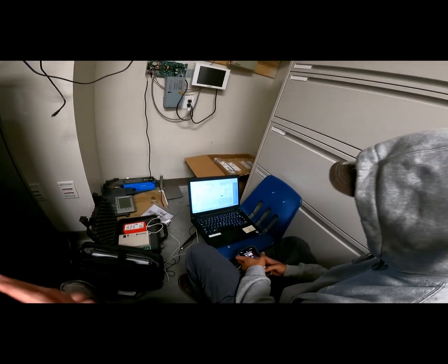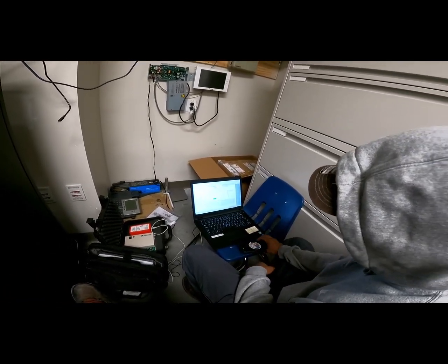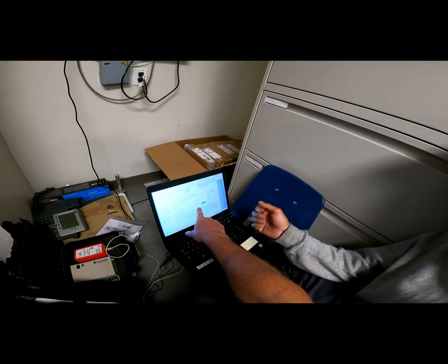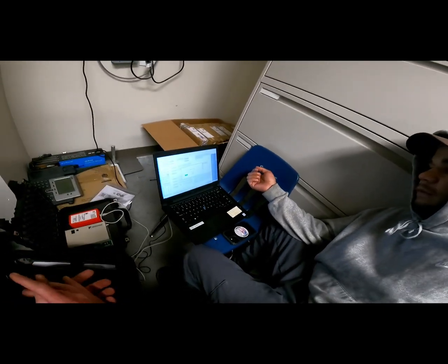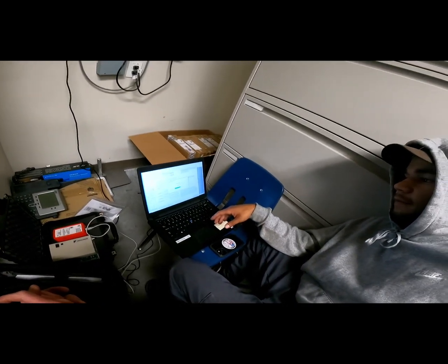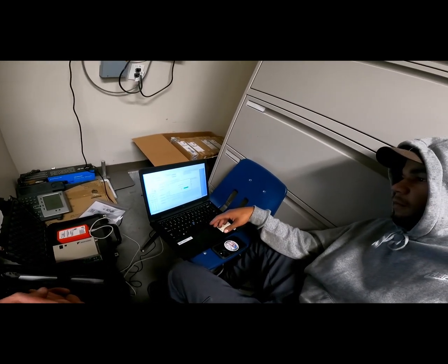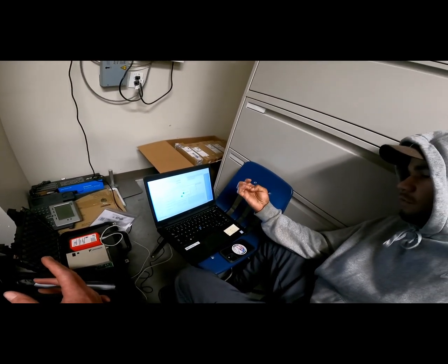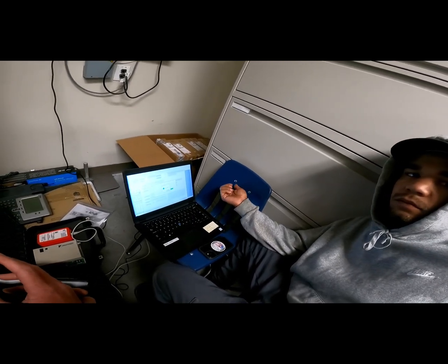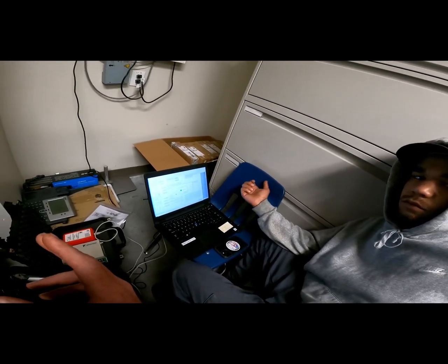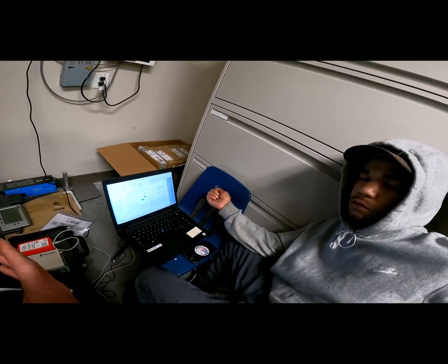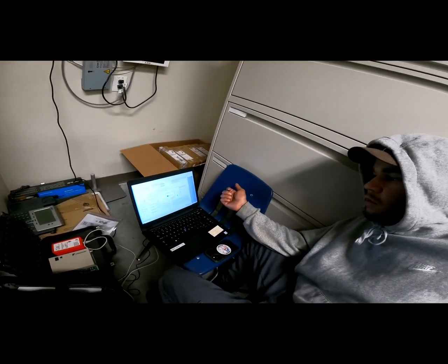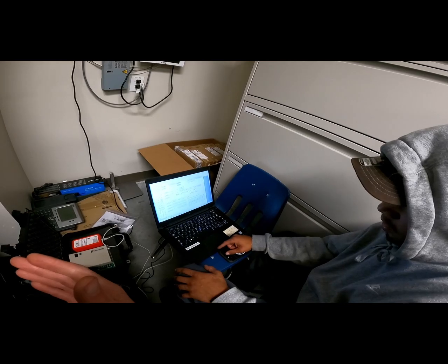One thing you need to make sure you do after we run a test on this system is that you go back to drive operation and reset all those units to operation. What do you think will happen if you don't do that? They're going to keep running in cool, full cool. They'll never stop. Now, the occupants may have thermostats or remote controllers that have their adjustability locked out. And if they're locked out and they can't mess with them, then they're going to start getting cold and try to turn their temperature back up, and they won't be able to. Sometimes those things are unlocked.